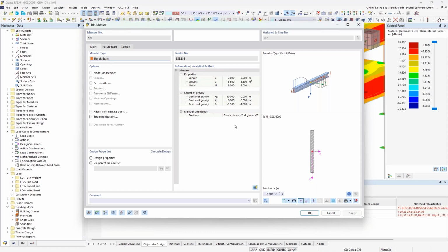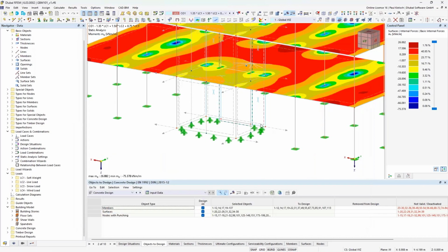In the current development state, we are able in the concrete design add-on to design this section, so to enter the reinforcement for this rectangle section, and then afterwards to perform the design checks. Of course, you may be asked yourself, why haven't we selected also the combination of this wall, and this wall? So maybe you would expect a shear wall with a member with a section of C shape or L shape, like I would have selected just these two surfaces.